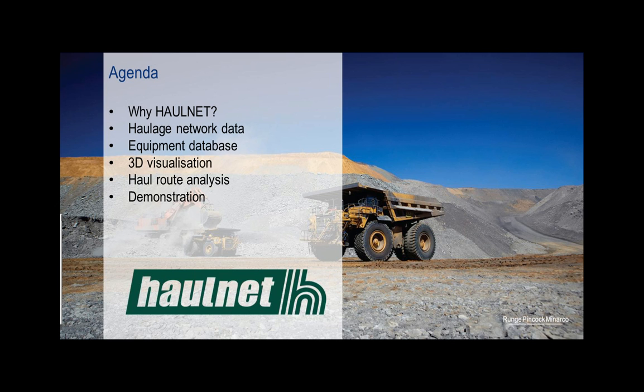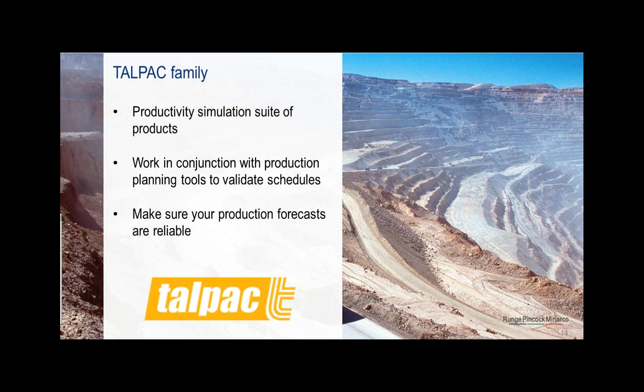So most of you would have used TALPAC or seen TALPAC in your careers. It's a productivity simulation suite of products. Obviously, you're looking at trucking and haulage simulation. It works in conjunction with your production planning tools to validate schedules, and of course in our case that's XPAC and Exact. But of course you can use it with any other planning software products out on the market. And the reason you're doing this is to make sure your production forecasts are reliable and you can plan for things like travel times and truck hours and choosing the right kind of fleets.